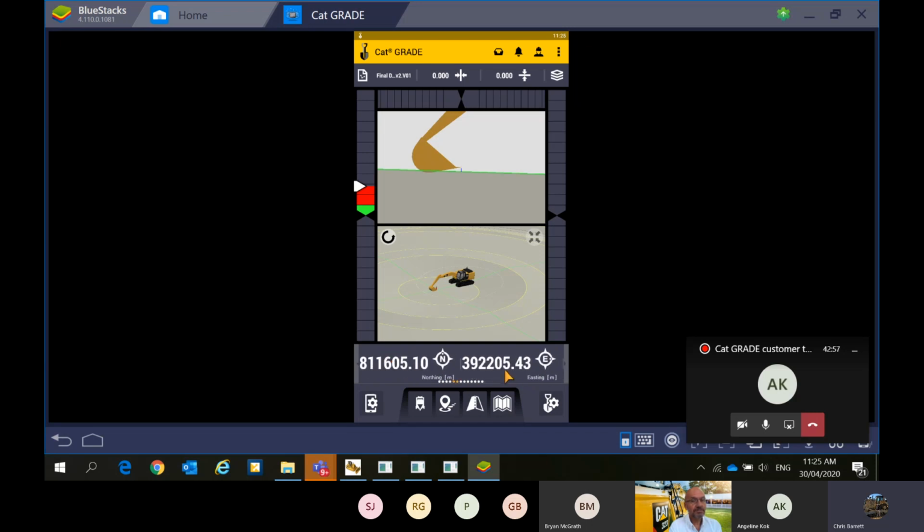There is. One thing we mentioned earlier was the Connected Community, or having a subscription to Trimble Works Manager or Trimble Connected Community. That enables the design file and the data from the machine to go two ways between machine and office. So if you've got a big job with multiple design iterations and you want to make sure everyone is up to date at all times, having that system saves a lot of time for the surveyor running around with the USB updating machine files.